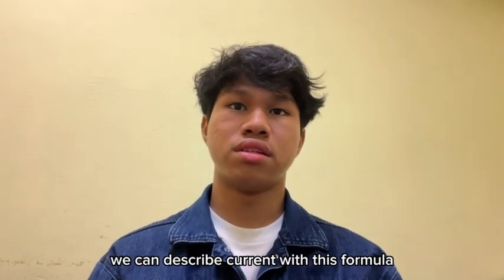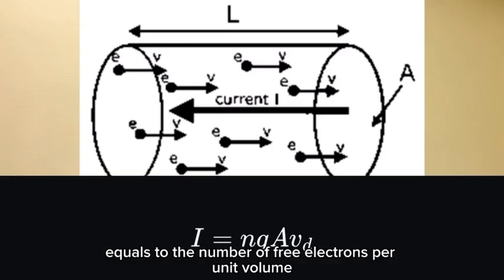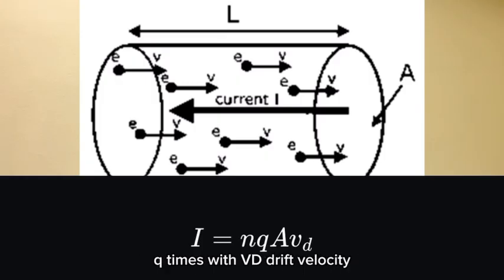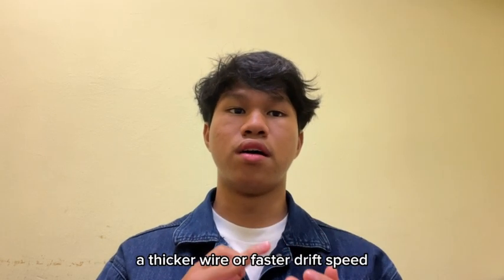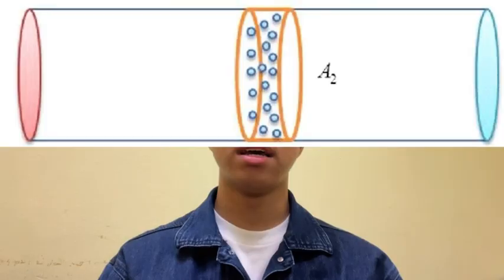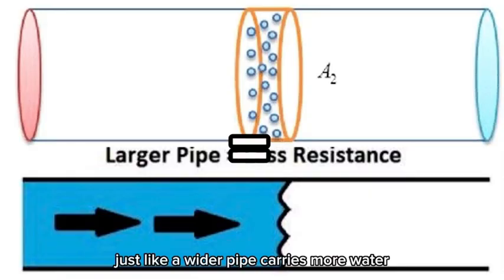We can describe current with this formula: I, or current, equals n times A times q times Vd, where n is the number of free electrons per unit volume, A is the cross-sectional area of the wire, q is the charge of an electron, and Vd is the drift velocity. This shows that current increases if there are more electrons, a thicker wire, or faster drift speed. That's why thicker wires are used for higher currents. They allow more charge to flow through, just like a wider pipe carries more water.